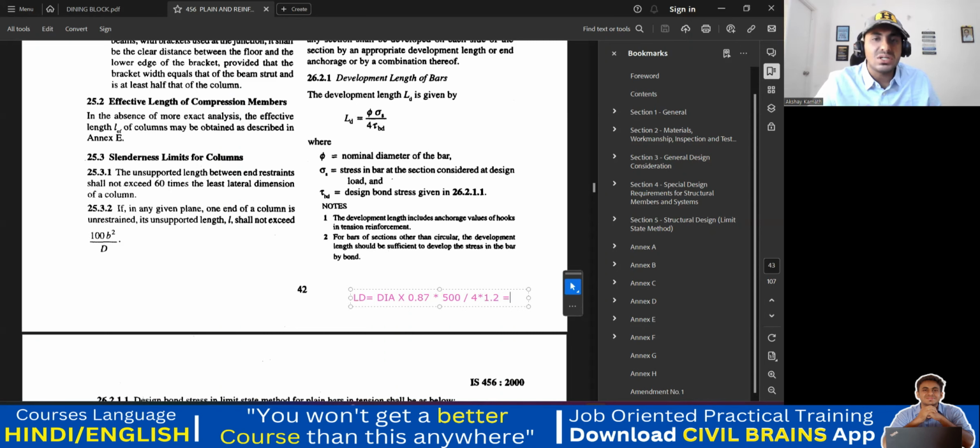Dia you keep as it is. Sigma stress is 0.87 into Fy. I'm taking 500 rebar. Divide by 4 times the 1.2. So I'm getting 90.625. How come it is 90.625? And it is wrong, no? 90.625 cannot happen.